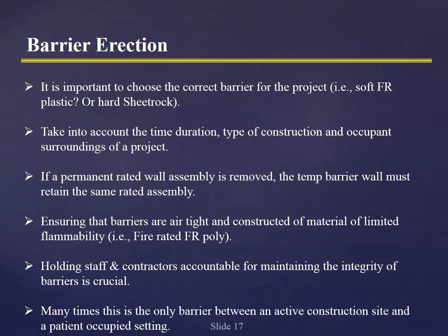Again, ensuring that barriers are airtight and constructed of material of limited flammability. This is another thing we sometimes miss. It has to be fire rated poly. It just can't be poly we bought down at the local hardware store.